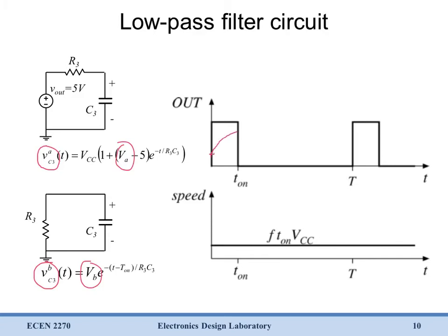Right, as we start out giving this positive voltage like we've seen before for this equivalent circuit, the output is simply going to rise. So this average value, this voltage right here at this node, is simply going to rise with some time constant until we transition into our second state where we have this equation, and our voltage is simply going to droop like that and fall down.